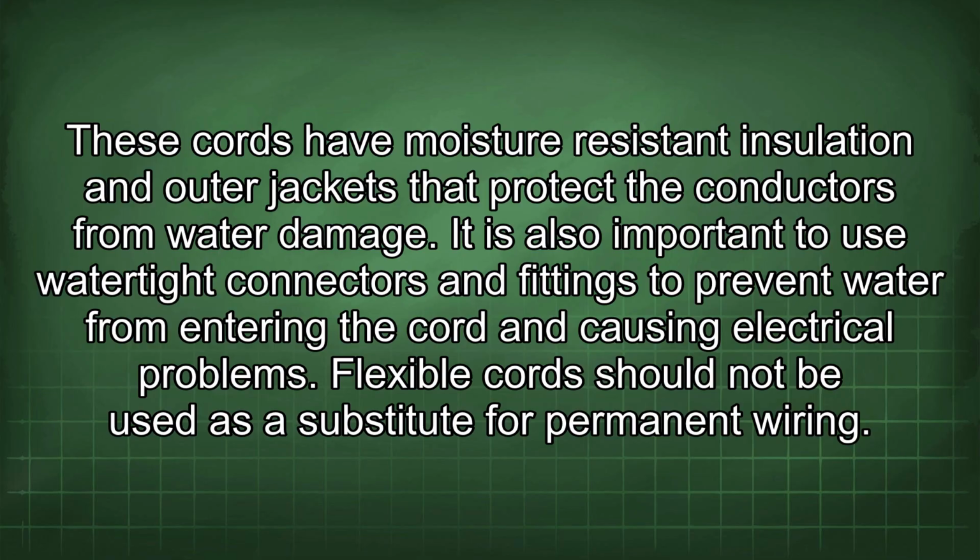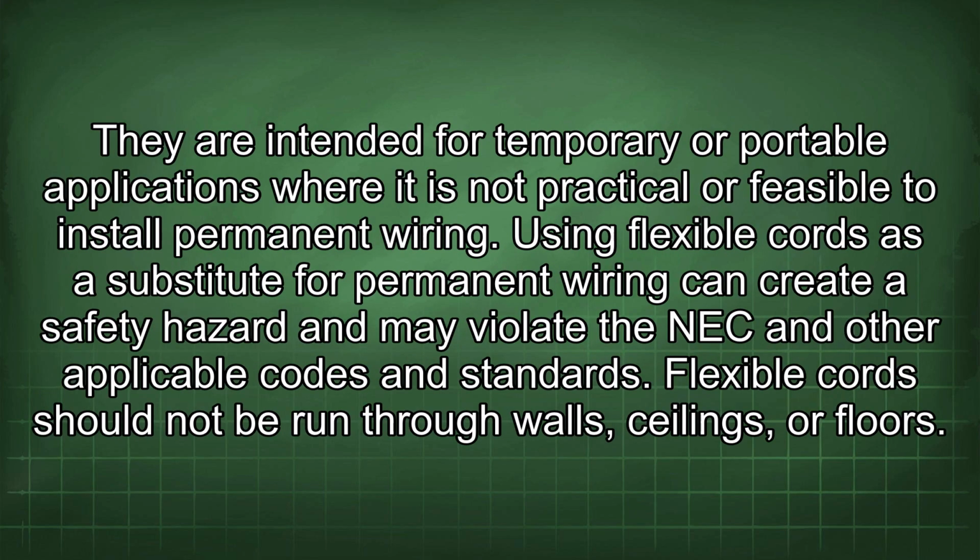Flexible cords should not be used as a substitute for permanent wiring. They are intended for temporary or portable applications where it is not practical or feasible to install permanent wiring. Using flexible cords as a substitute for permanent wiring can create a safety hazard and may violate the NEC and other applicable codes and standards.